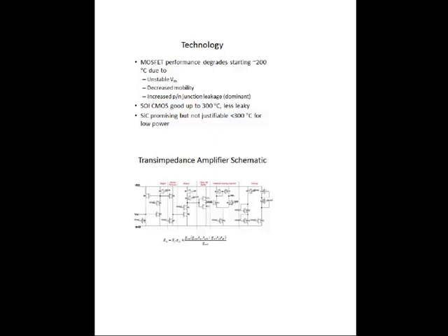The advantage of this topology is that normally you put a resistor in a negative feedback path from input to output, but that resistor loads your amplifier. Here, this doesn't load the amplifier, plus biasing is easier, and most of the input referred noise comes from M4.